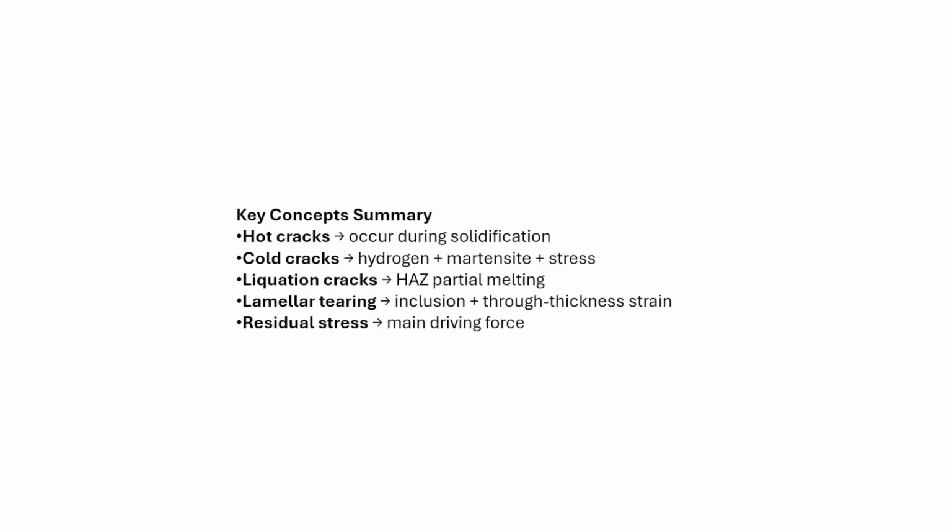Okay, so for some of the key concepts from the first lecture of this week: hot cracking occurs during solidification, cold cracking occurs due to hydrogen embrittlement or martensitic phases and stresses. And liquation cracking is in the HAZ region. It occurs in the HAZ, not the weld material, and it occurs in high heat input welding processes.